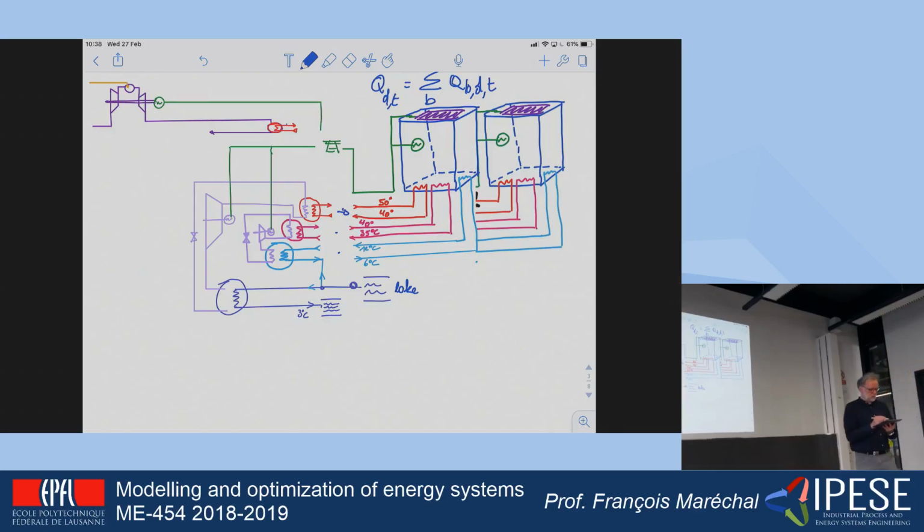Okay. The same for another heat pump that is perhaps going to produce the cold or use the cold directly, so it depends here if I'm making a connection or not, okay? And it can supply the heat to the lower temperature system, okay? And at the end, I will have to make here, at this level, the sum of all the electricity consumptions that I will have. I will have to sum the contributions of each of the heat pumps in my system to the sum of all the demands of all the buildings in my system, okay?